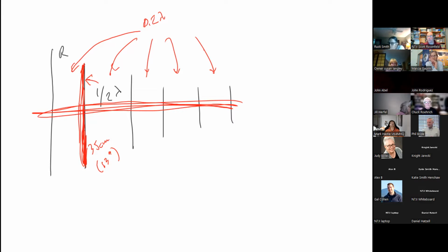Okay, so how do the different elements contribute if they're not conducting? They are parasitic. They're in the field. Basically, you have this radio frequency energy, an electromagnetic field that's generated. This one is the reflector. It's slightly longer, and when it is spaced a certain distance apart, it will tend to resonate and cause a reflection back in the forward direction. That's known as a parasitic element.